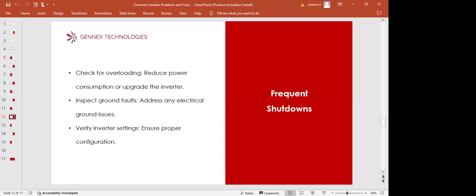And then if your solar cable is leaking, that's why we developed how to test for leakage in your solar panel. And then you check if your earthing is proper, because they can make your inverter come up, go off, come up, go off, and then eventually the inverter will get damaged. Now, verify inverter setting, because that one too can cause it. Like I've been emphasizing on the other point, it is important. Make sure you program your inverter very well.